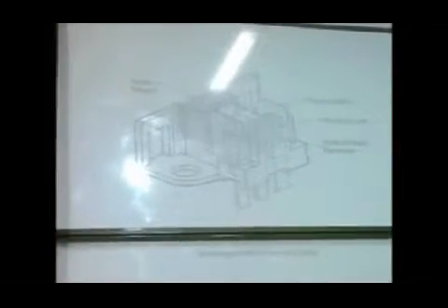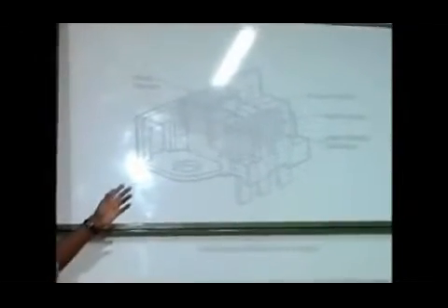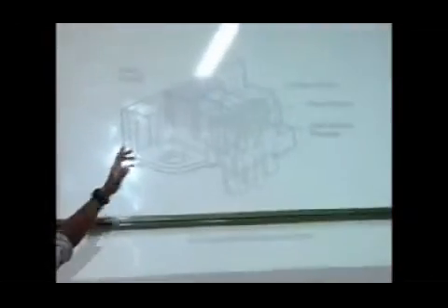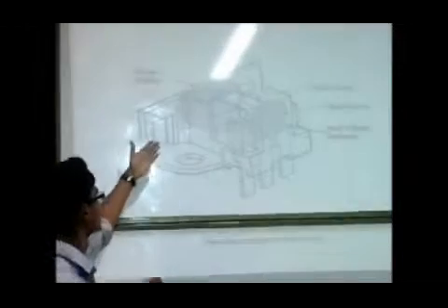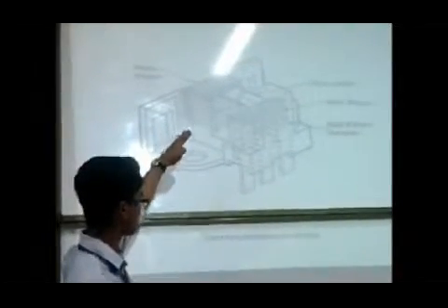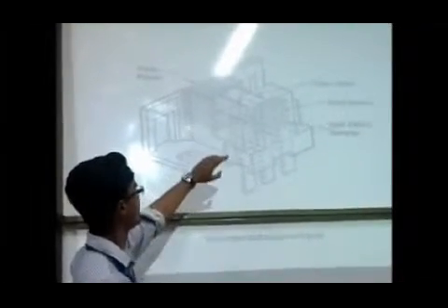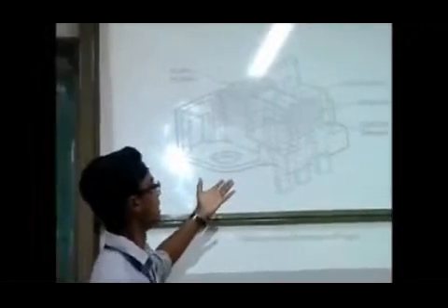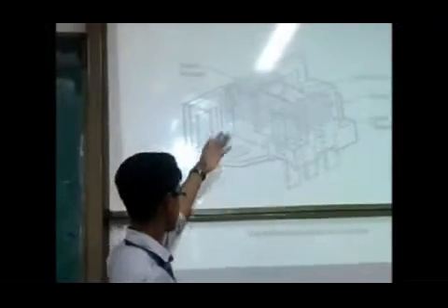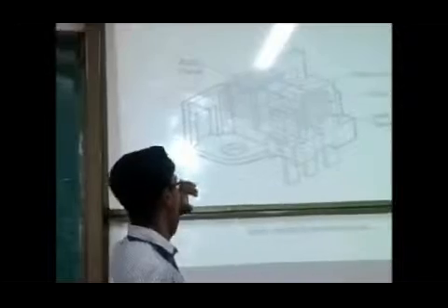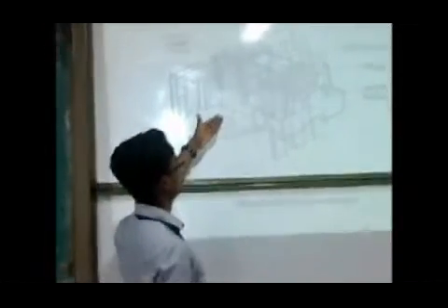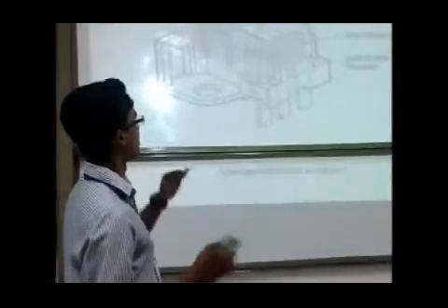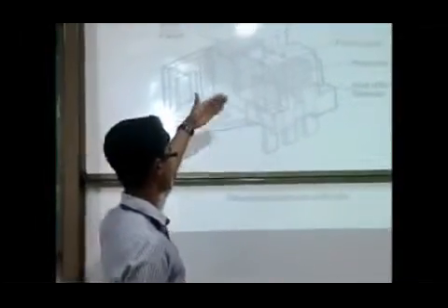And here we are adding more pieces to this, and the working is like this. The magnetic flux lines start from the magnet, cross the gap, and reach the south pole of the feedback sensor, and actually the north pole is on the magnet. So in the normal case, when the vane is not in this gap, the sensor will remain in the on position because the magnetic flux lines are undisturbed.